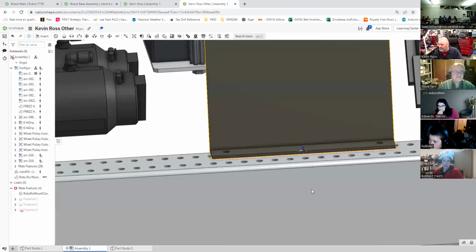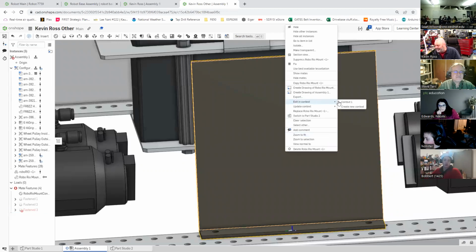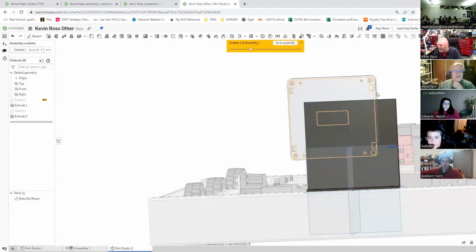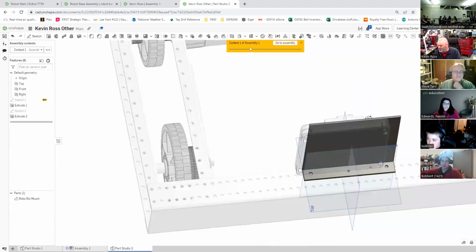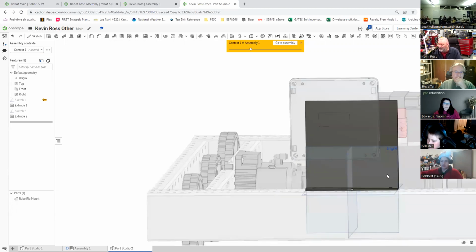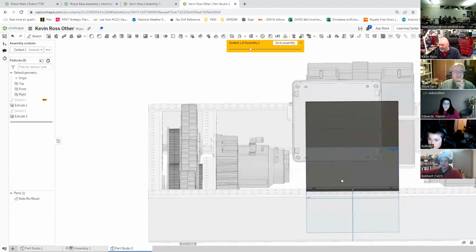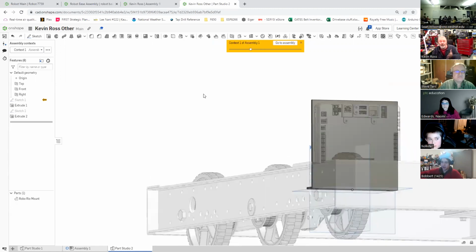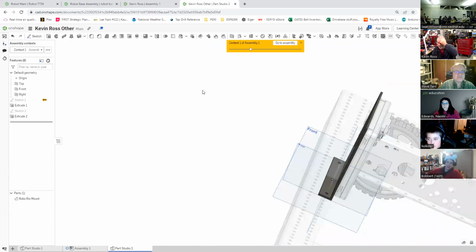So what I'm going to do is right click this guy and edit in context, because remember we created a context for it. Context 1 is what it's called. That's its default name. So there it is. But notice that this thing is no longer where I wanted it to be because I moved it. And one of the things that you do a lot of is you go, okay, what do I do about that? If I come over here to this context thing, I can click on the 3 dots and tell it to update its context. And when it does that, hey, what did it do? It successfully updated the context, and now it moved, right? So the context has moved and it's now useful.